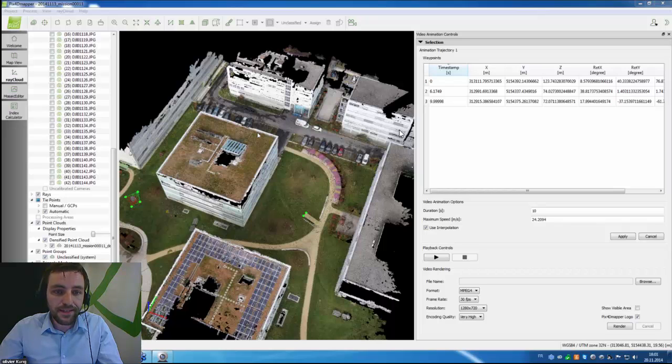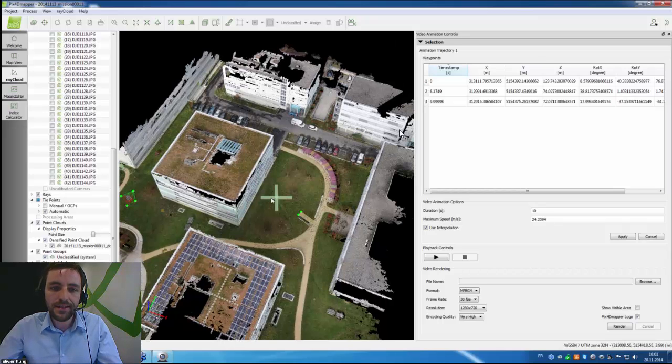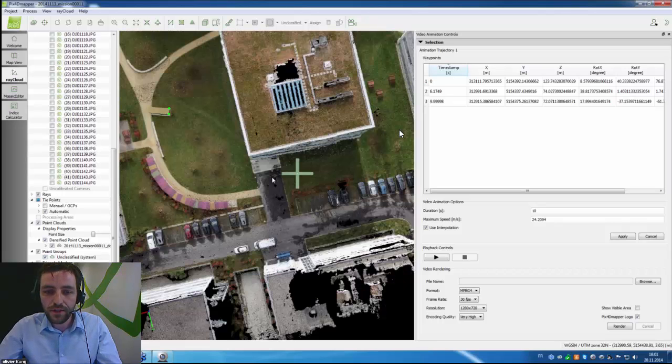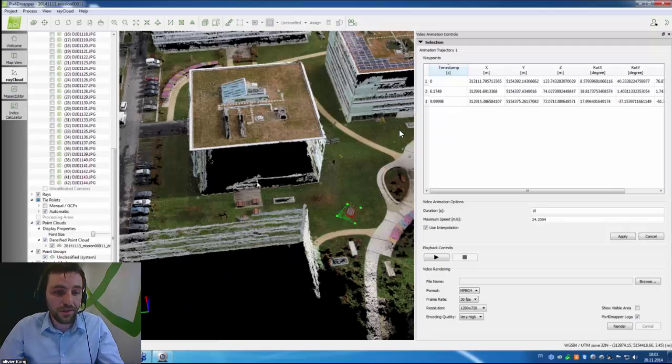There appears to be missing data in the model. How do we mitigate that? That's a good question. Right now, why is there less data on some parts of the building? The reason is because the overlap at that spot was not enough. The best way to mitigate that is in a next update of our Pix4D Mapper app flight planning software. We will let the user set settings to take more images when you have such a difficult object such as this building.